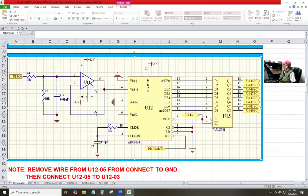Now, why do you need U11? It's just like a safeguard. We make sure this signal is not screwed up. That's why they're using the amplifier. And the other thing, who can tell me why I need capacitor C3? To make it steady.